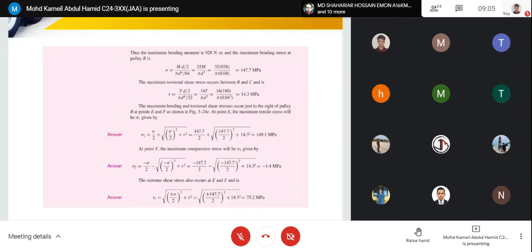Then for the shaft or pulley, that is the method to calculate your shear stress: get your T, the torque value, and use the equation. Sigma from the bending moment is going to be your sigma x, and then you can use the sigma 1 equation from the Mohr circle stress transformation.